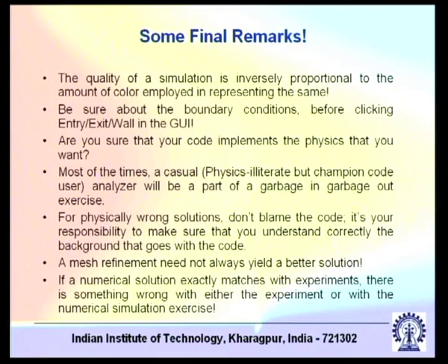But joking apart, if we take it very seriously, many times we are not very careful about the authenticity of the results once we get nice plots, and this is something which is very deterring. One should be very careful about the physics that has gone into the CFD code. Once you consider the physics, one of the important considerations that comes is the boundary condition. Be sure about the boundary conditions before clicking entry, exit, wall in the GUI, or inflow, outflow, wall.